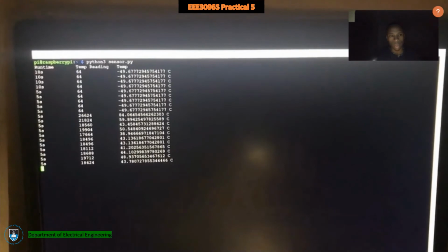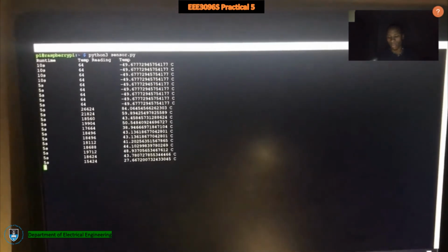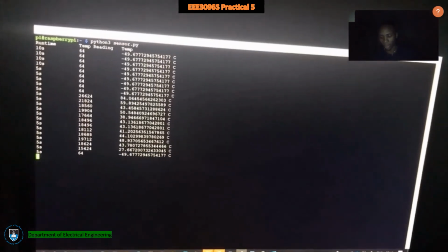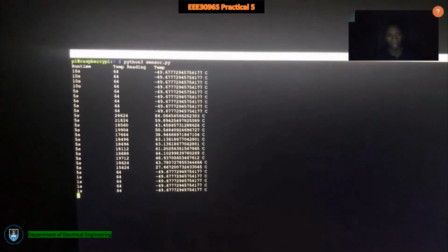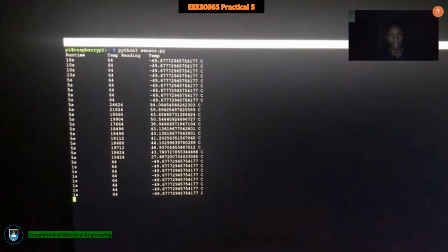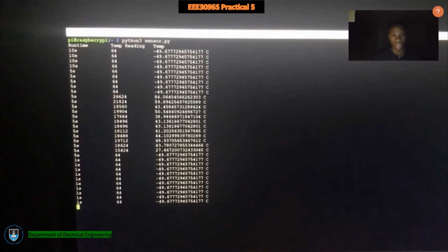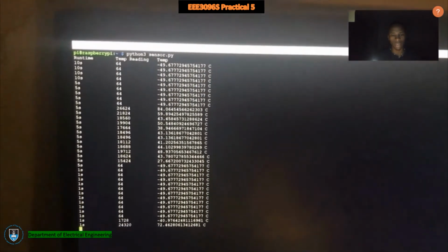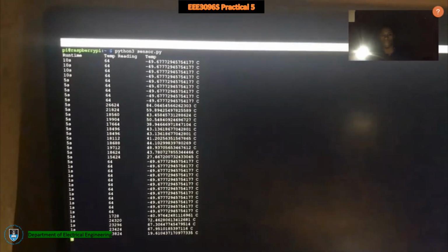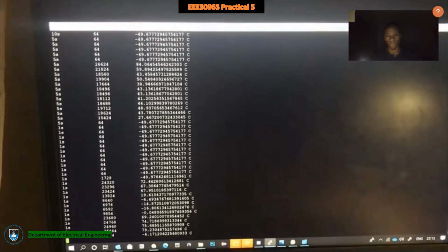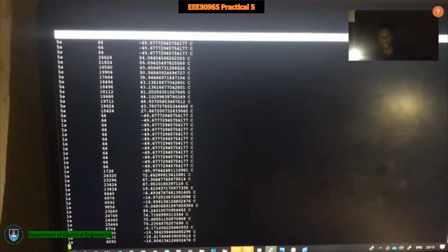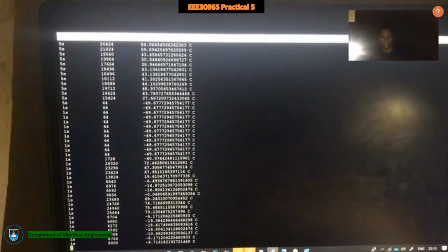So now we'll make our readings faster by clicking to set the time interval to 1 second. As you can see, the flash was off and we're getting negative values, and then when the flash is on top of the LDR, we're getting high values. Moving the flash a little bit back, the values drop, closer, the values increase, and then back, they drop down to negatives, and then closer again, they increase.